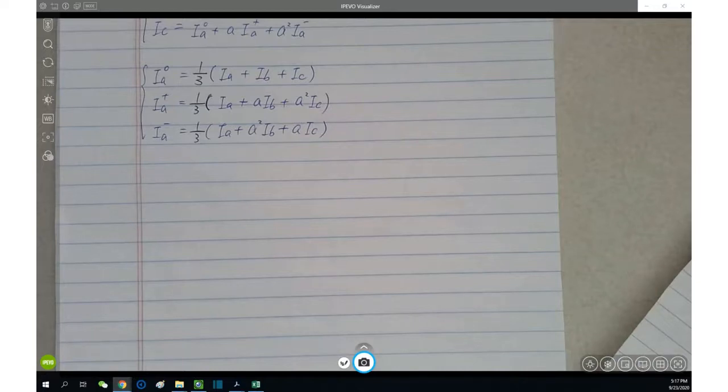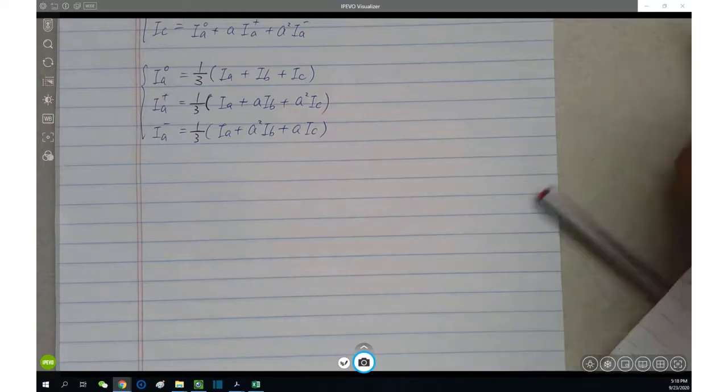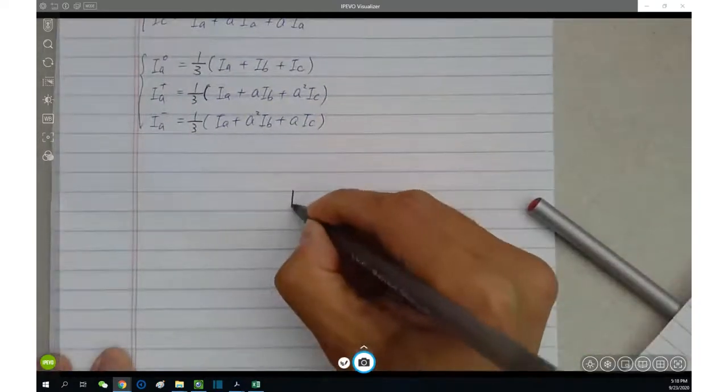If I needed to shift the phase, you need the smaller capacitor. If it's asking for 0.95 lagging, then you need a smaller capacitor. You don't need to do that much. So basically somewhere in the math, mine should be off then. Of course. You're basically thinking this way, right? You see the middle as well, unity.